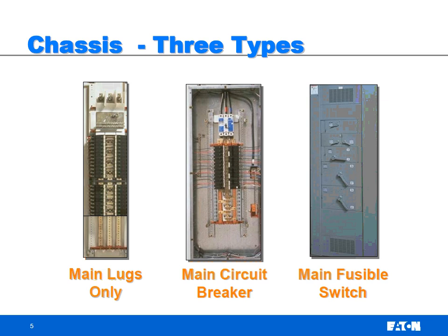Then you run into the safety factor. If I come back here, open the breaker, and run back upstairs, and as I'm going to work, my buddy just got off break, he walks into the switchboard and sees this circuit breaker open. Why is this breaker open? Lockout, tagout procedures, and all this other stuff can come into play. So one of the things to consider between main lugs or main breaker is convenience of disconnect.